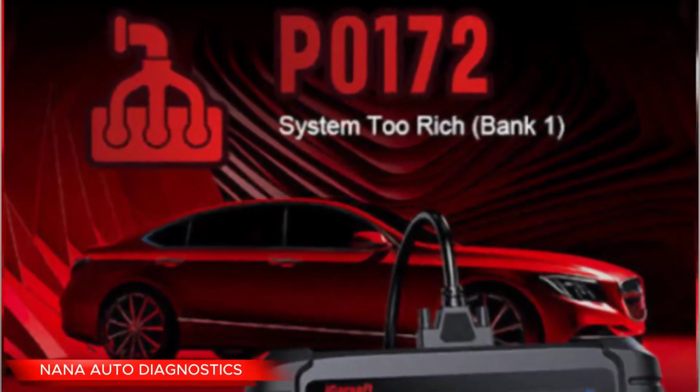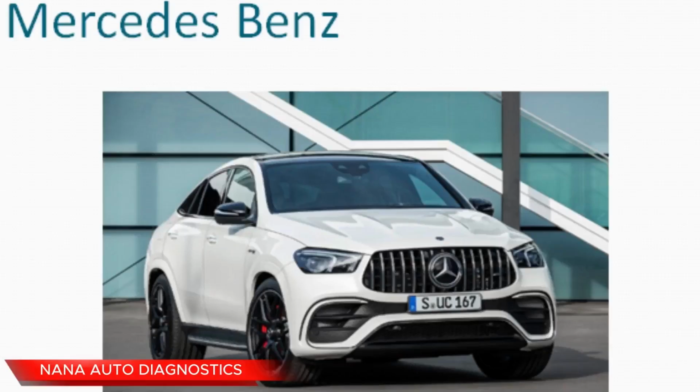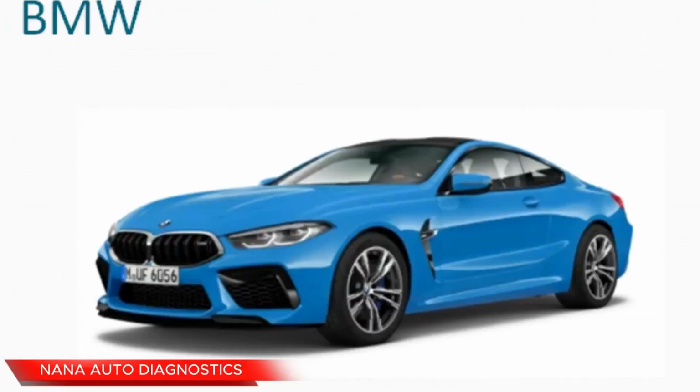Right now, if you retrieve a P0172 code, we know that that code means the system is too rich, meaning that the engine is running too rich, irrespective of the manufacturer. It can be a Benz, it can be a BMW, it can be a Nissan.